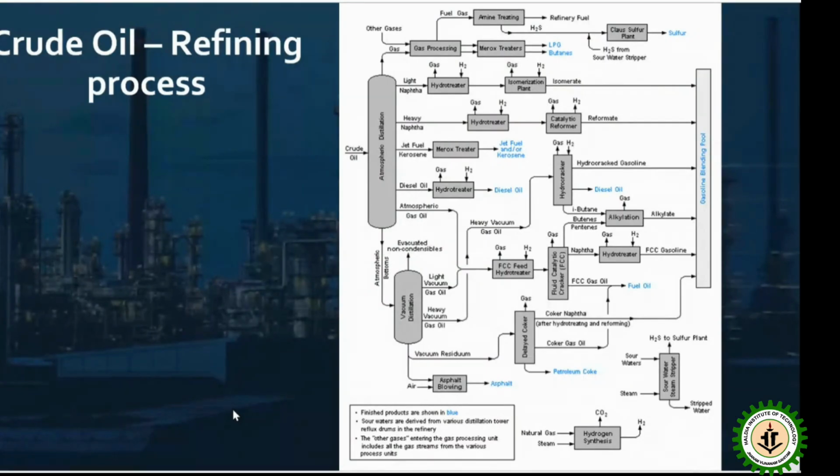No. That's why on each tray in the distillation column, there will be local heating, and that is called a temperature hotspot. If a temperature hotspot generates inside a ceramic column, yes, you are correct, it will create a lot of cracks on that.